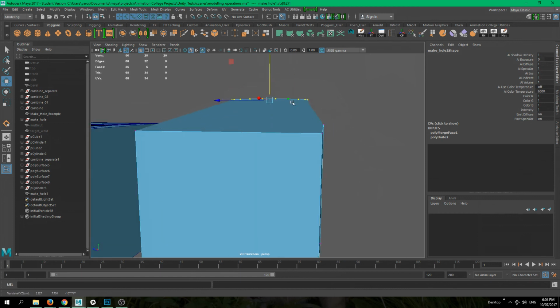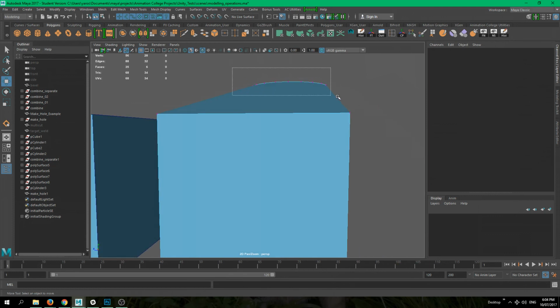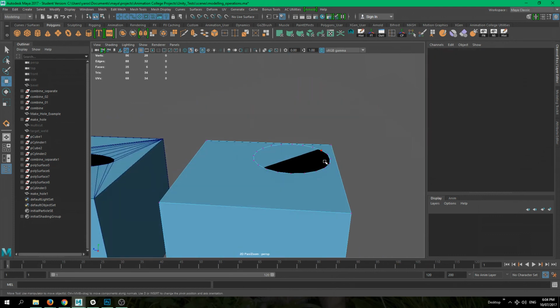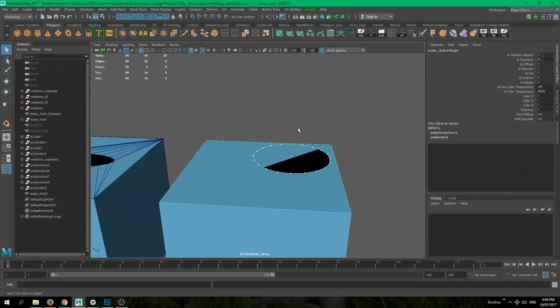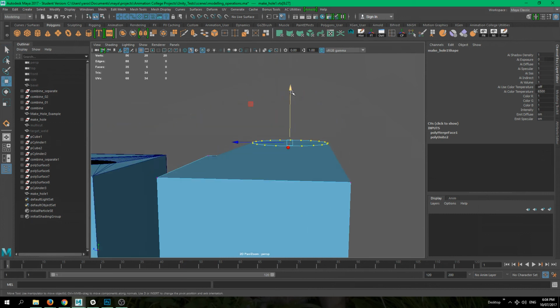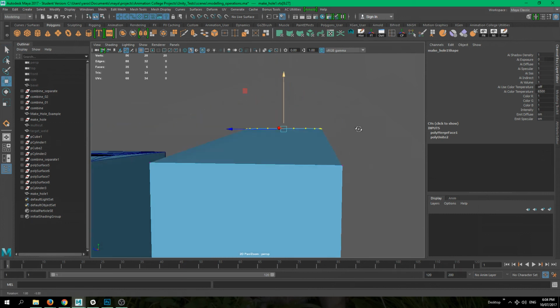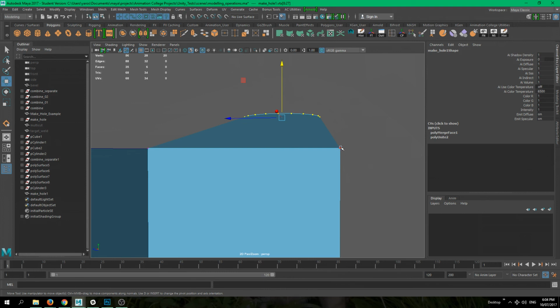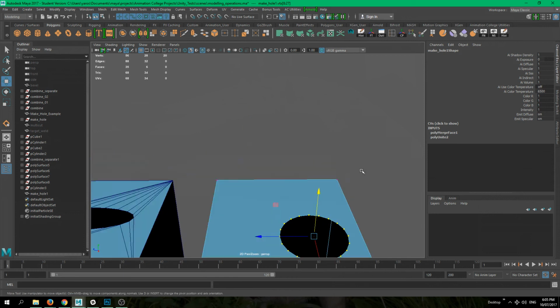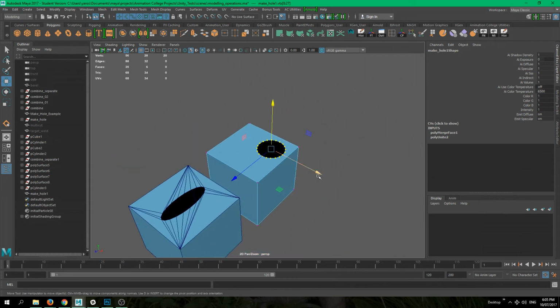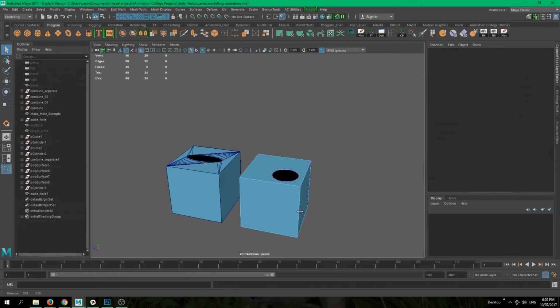So once again, if we move them out, we just need to drag select all of them, or potentially I think you might be able to select them like this. Confirm which axis you're working with. Navigate to the vert that you want to snap to. Press V, and middle mouse click on this one, and kind of middle mouse click and hold and drag around, and you will see that your vertices will get snapped to this point. So snapping is one of those things that you need to practice, and you will get used to it quite soon.